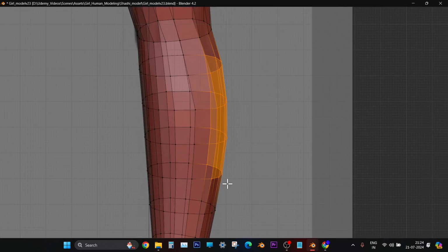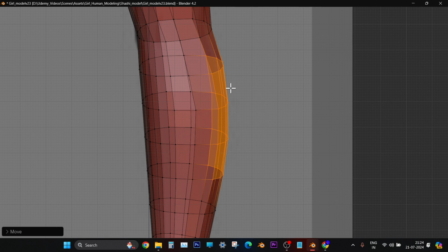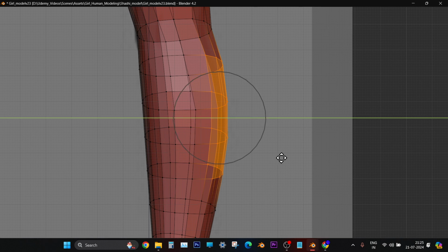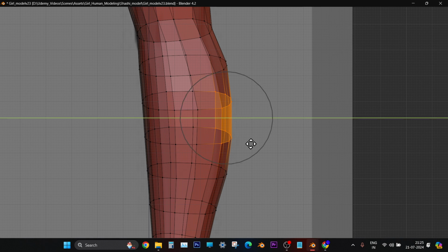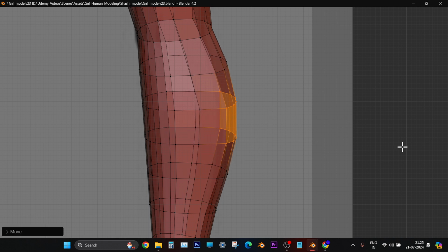Since we have got this curvature, we can move it a bit backwards altogether. All the four lines of edges I'm selecting, then moving all together like this. And again, I'm deselecting the top one and the end set of vertices, and the remaining I'm using for more bulging.